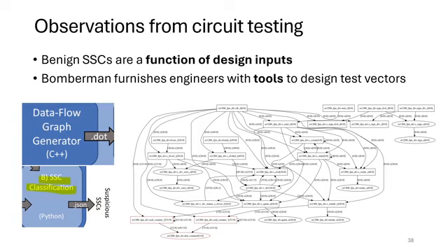Most often the false positives they found were a function of just design inputs that ended up not changing during the test. This means also that repeating test vectors over and over again, using those LFSRs, the linear feedback shift registers, is a feasible approach. For data path inputs, they just have to repeat the test vector to eliminate the combinational logic that's suspicious.